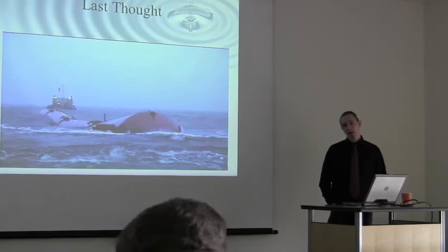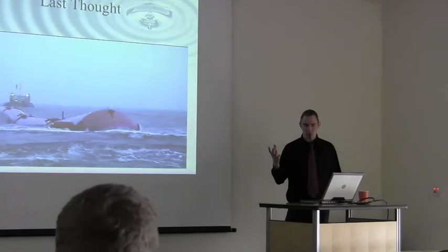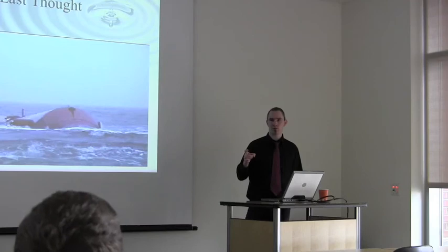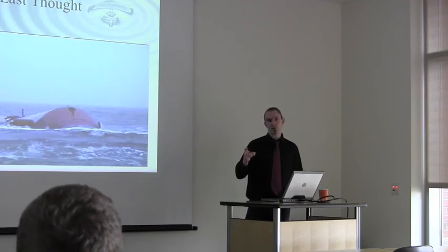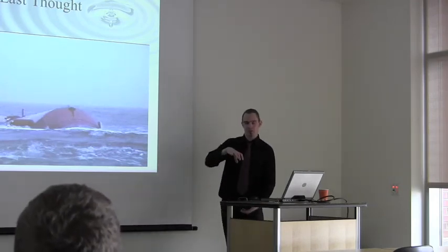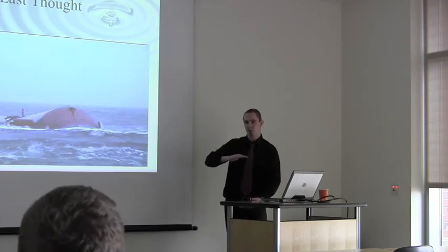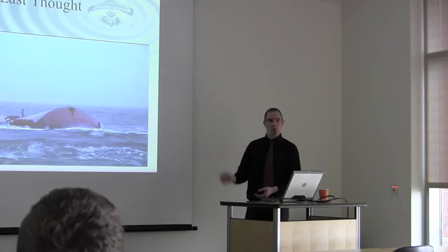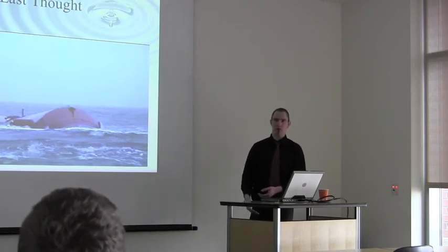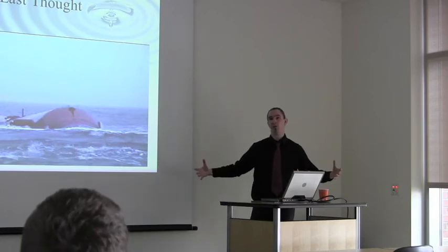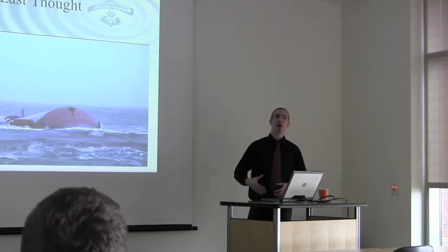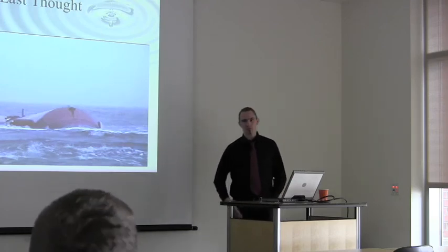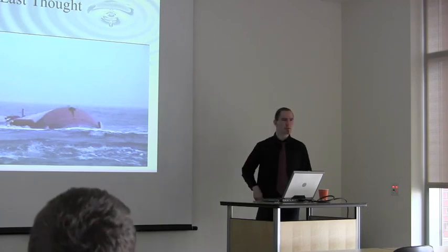The spar also is not a good wave radiator. If you look at the cross-sectional area through the surface of the water, it's actually very small. So as it moves up and down, most of the displaced volume is across the area of the bottom of the goalposts, and it just circulates. As you move up, the water at the top moves to the water down below. So you're not generating a wave that way, just generating friction, which is why the spar works so well as an inertial reference. And the fact that it weighs 4 tons or whatever it is.